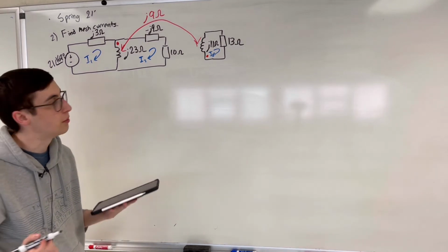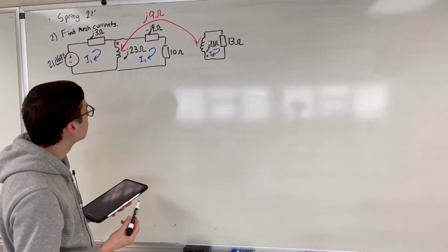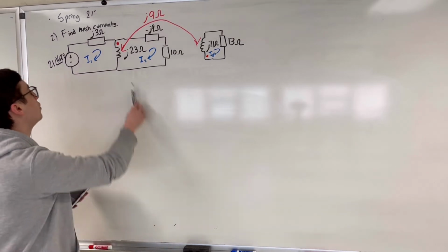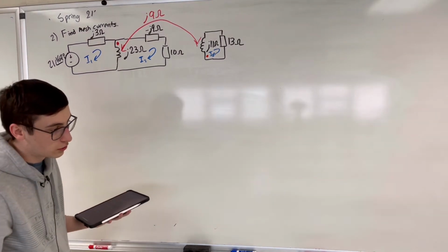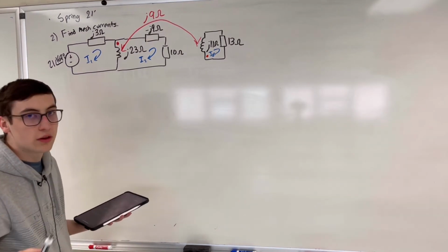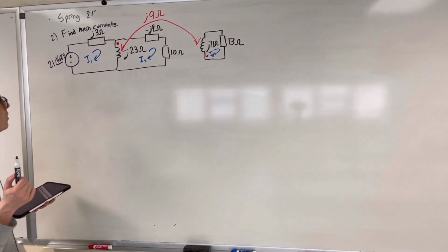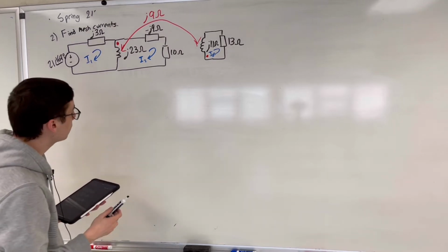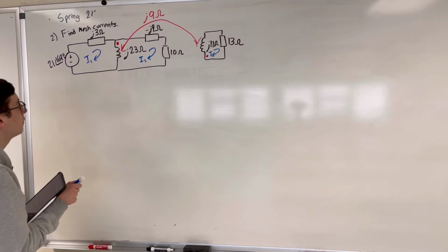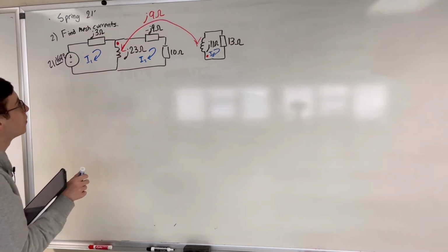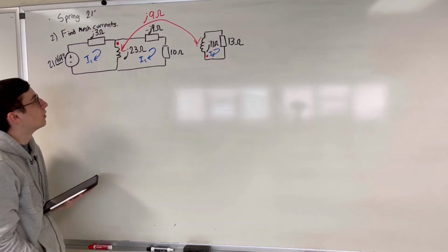Here is our second problem. It is a mutual inductance problem. So with mutual inductance, that means that these two inductors are acting on each other, and you have to introduce a dependent source into your equation or into the circuit. So first, what we want to do is to define a current flowing through this inductor.